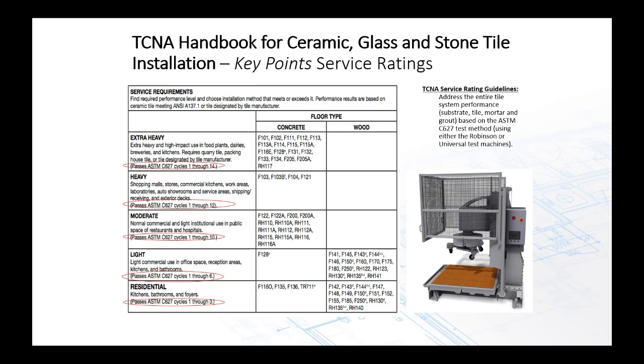If I put a 10 millimeter or 3/8 of an inch, 1/2 inch recycled rubber sound membrane in that same system with the quarry tile, thin set, and so on, you wouldn't expect it to go extra heavy. I would expect it to go moderate at best. So that's how we rate how these different components come into a flooring system and how it affects the performance or wear on that system. Hope that makes some sense.